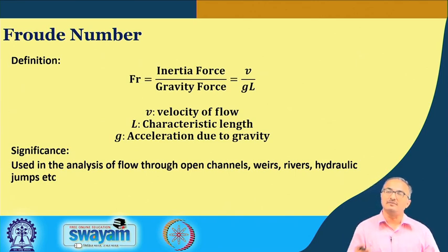In this we have the effect of gravity, because you find that only in unbound liquids there will be wave formation. Okay, wave formation does not come in a conduit flow. When there is flow through an enclosed pipeline, there is no wave formation, unless you have two-phase flow. Only in two-phase flow could there be some kind of wavy flow, but that has two phases, not a single phase.